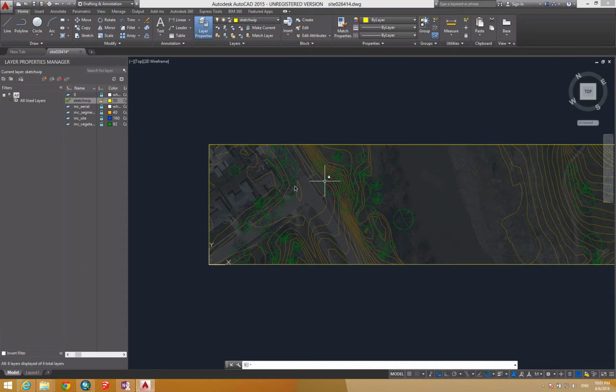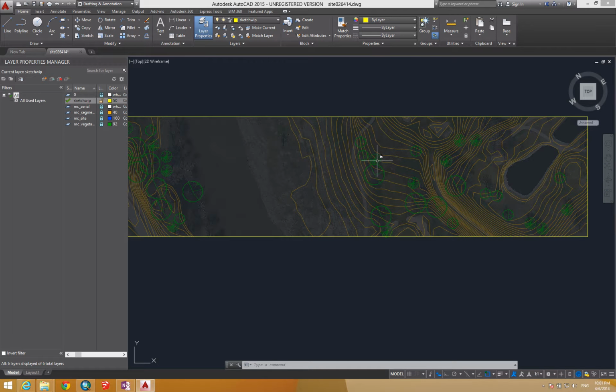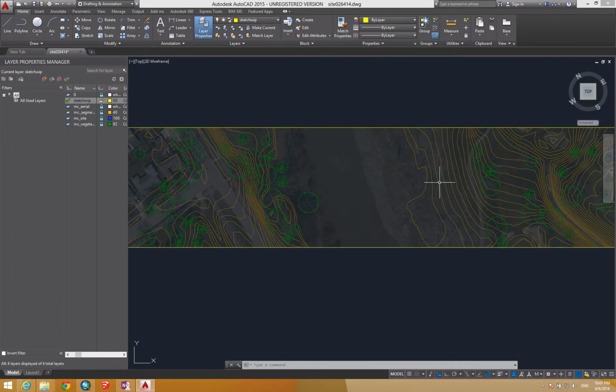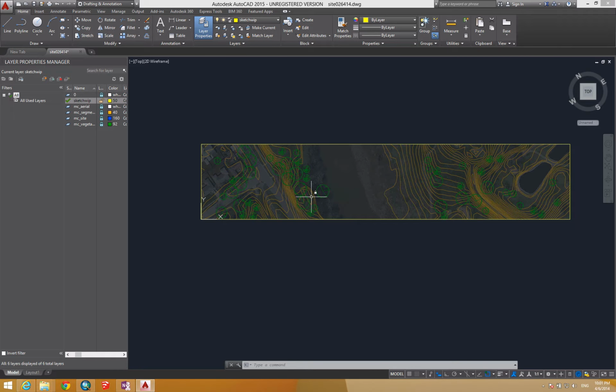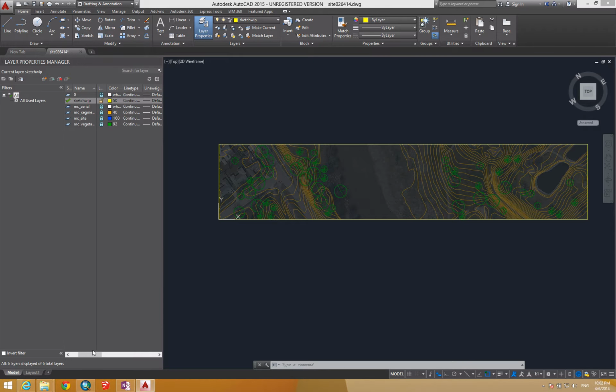It's kind of a flat ridge, but that might make more sense to have a pathway follow that to come down to this area. And on this side, the topography obviously ramps up really quick right around here. So I would probably want a pathway to be closer to that. Another thing, I don't really want to accidentally snap to one of these contours, and once I've got a pretty good sense of where they are situated, it would probably make sense to freeze those layers.